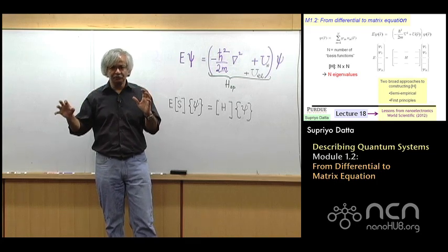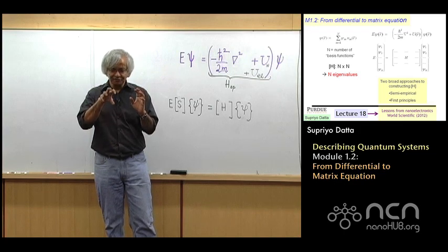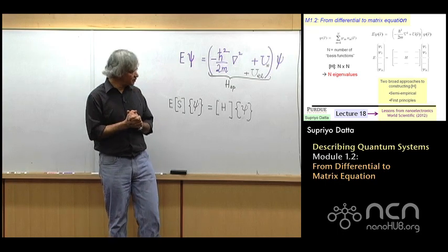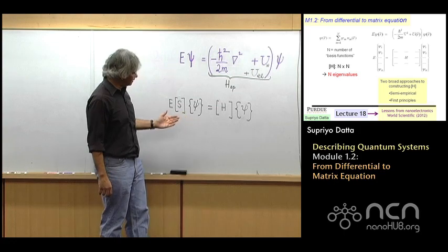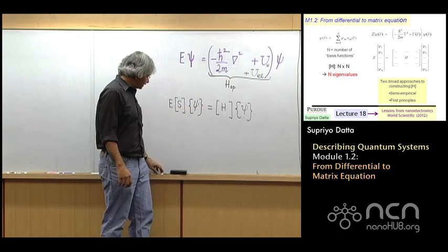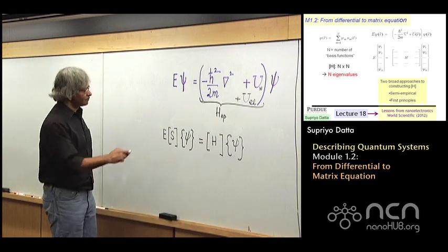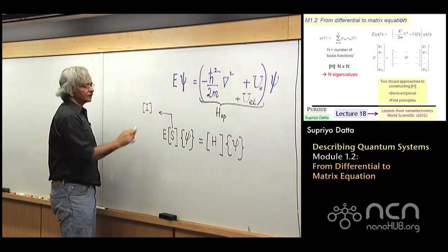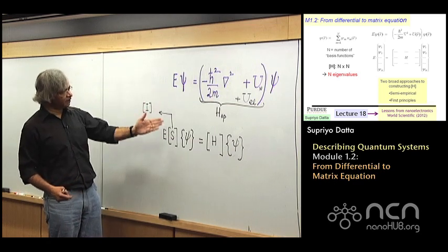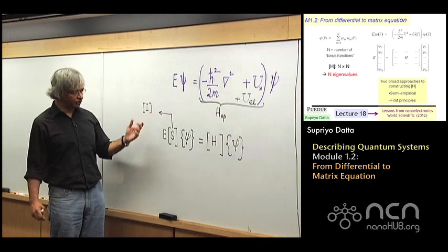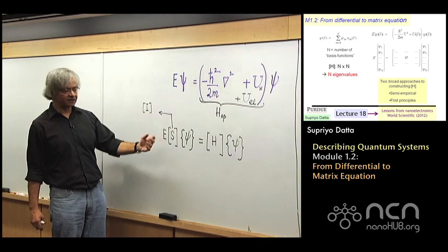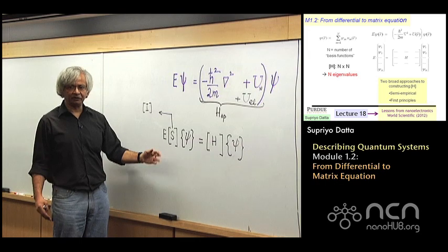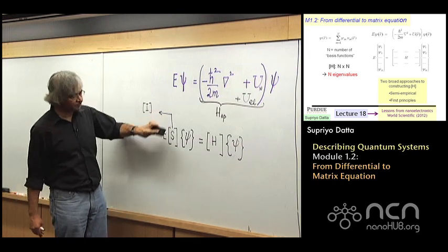And in order to illustrate how you do it, of course, we need some proper description of the channel so that I can tell you how to connect the contacts and all. And as far as that description is concerned, I'll use the simplest one, namely the semi-empirical methods, where generally the way it is done is that this S matrix is assumed to be an identity matrix. Identity means a matrix whose diagonal elements are 1 and all other elements are 0, which basically means you can drop this completely. Because for matrices, this identity matrix is like 1. So in a product, 1 can be dropped. That really goes out. So you can essentially drop that.